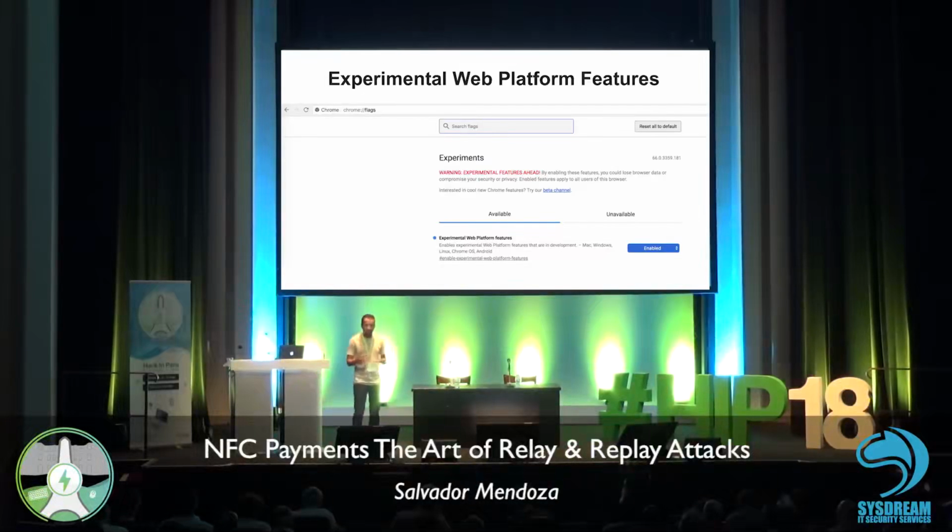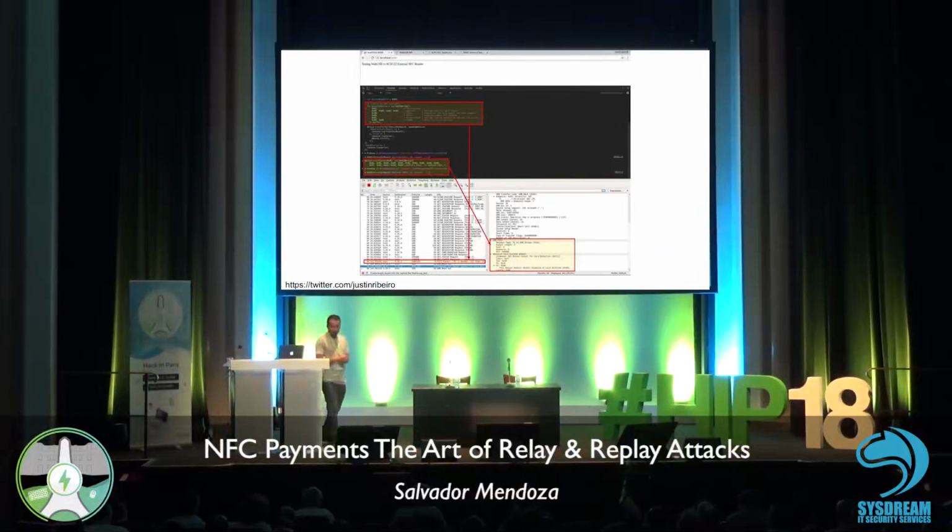It didn't work because it's very difficult to do, because you need to know about native commands, how to answer the questions for the device, but also answer back simultaneously without delaying. So in Chrome, it has this kind of tool that you can enable, experimental web platform features, to work with USB. So these are some of the issues that people are having connecting directly to the USB cable using a PN532 or ACR122 NFC reader, and it's very challenging.